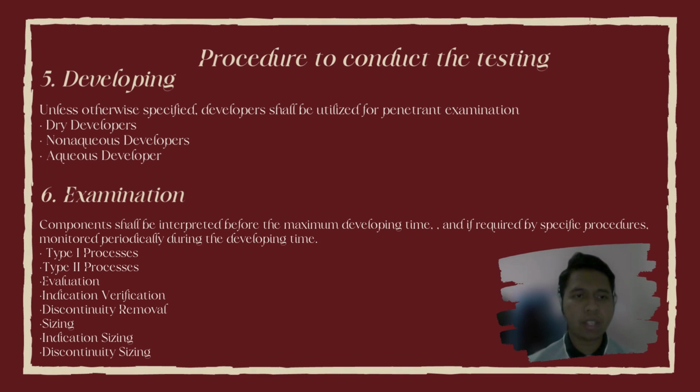Next, the fifth step is developing. Unless otherwise specified, developer should be utilized for penetrant examination. There are a lot of developers such as dry developer and aqueous developer. Next, the sixth step is examination.